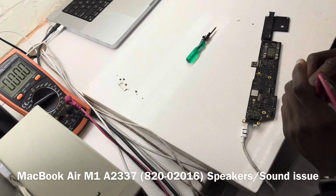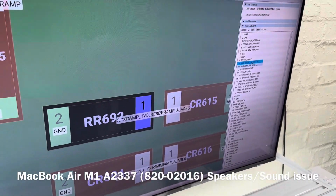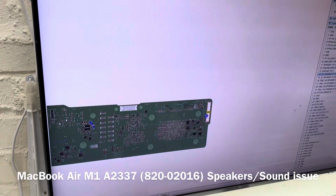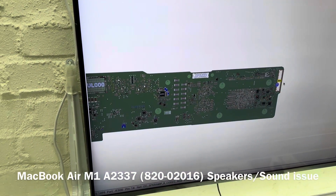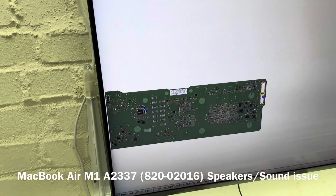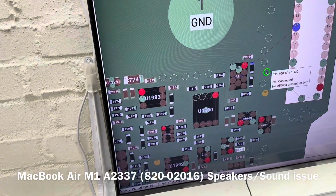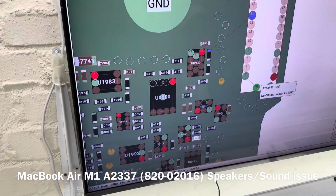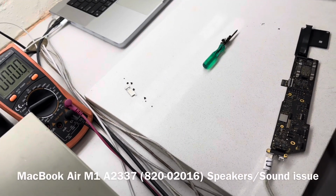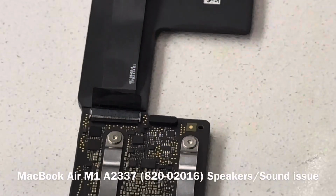And we have 1.7, so that means that signal is present. The next thing we want to do, let's see, what do we have on pin 14? Okay, it's pin 16. Let's see what we have on pin 16. We're supposed to have 1.8 volt also. Let's see, do we have that? And that we can measure at this component here.